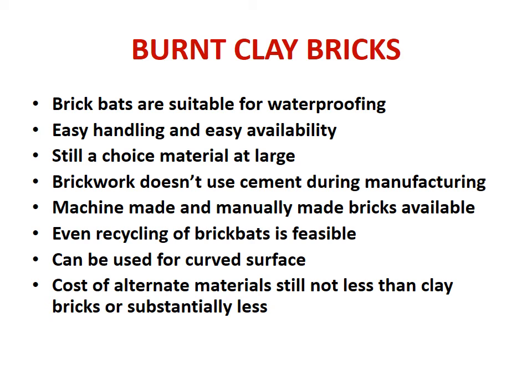Then brickwork does not use cement during manufacturing. Machine made and manually made bricks are available. Even recycling of brick bats is feasible, as we have just discussed in case of recycled CND waste. These brick bats are also recycled. And then this can be used for curved surfaces also because of the small size. And the cost of alternate materials is still not less in most of the cases than clay bricks, or not substantially less. There is minor variation. That's why burnt clay bricks are still being used in the country.